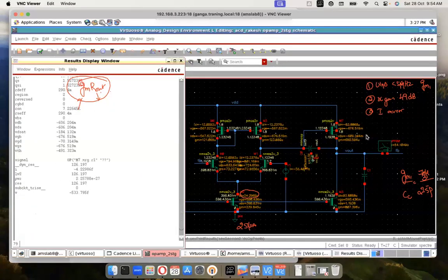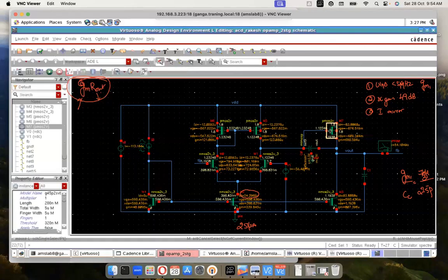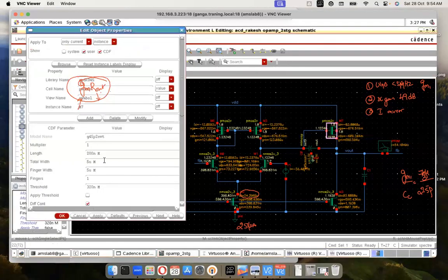So for the timing, what we'll do is we'll go back and say that, okay, now we figured out what the issue is: because of the VGS minus VT mismatch, which earlier during the calculation we had not taken into account. We are seeing some issue. Let's go back and put it at 32.